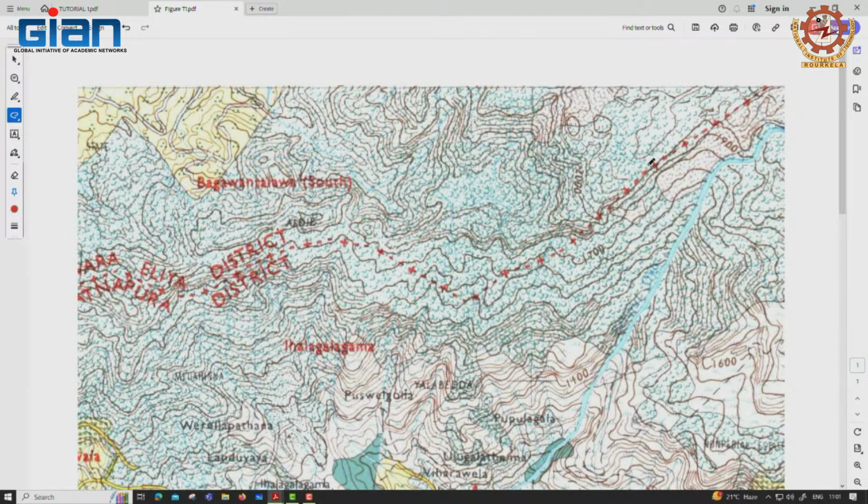There are many contours we can use, but it is up to the choice of the designer. We are asked to have about 100 to 200 meters of head. Between any of these dark brown lines it is 100 meters head difference, so we can select accordingly and select a suitable place.